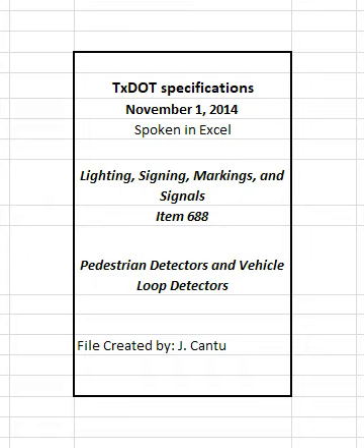3.2.4 Loop wire installation. When shown on the plans, place the loop wire in a flexible vinyl or polyethylene tubing in accordance with Article 688.2, Materials. The loop wire color requirements do not apply to wires in tubing.